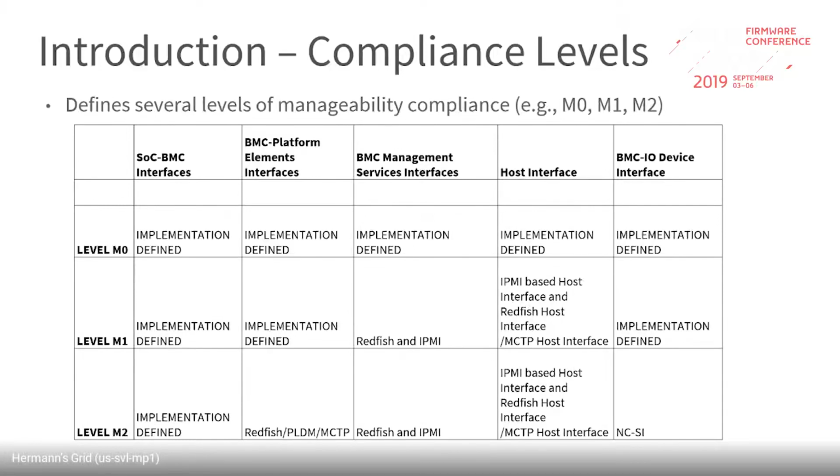So in our case, it's an ARM-based BMC communicating with an ARM-based host or an SOC. Currently, the criteria for the compliance levels are the interfaces between the SOC-based host and the BMC, the interface between the BMC and the platform elements, the interface to the BMC itself, and the interface between the BMC and the IO devices, basically the network controller, storage controller, or any other IO devices that you may have.